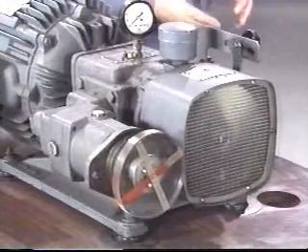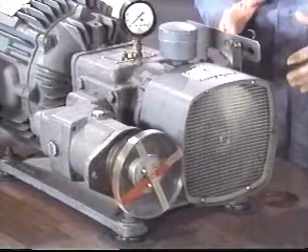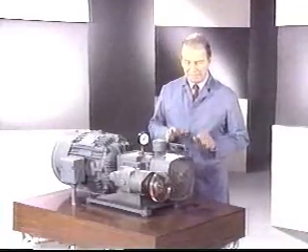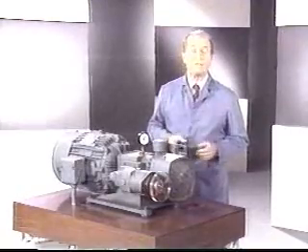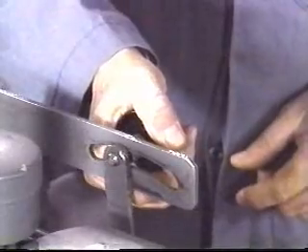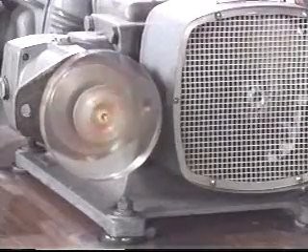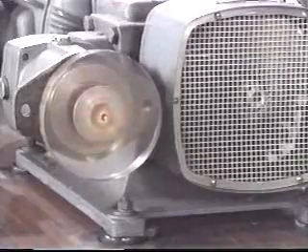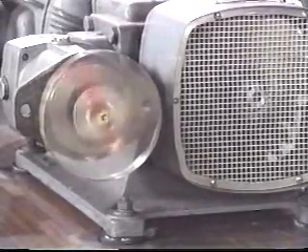Right now, the electric motor and pump are turning at 1800 RPM, but there is no movement of the motor shaft. Actually, we couldn't move it if we tried, because the pump yoke is centered, and its pistons can't move in or out of their bores. Moving the lever off-center causes the motor to rotate slowly. The more we move the lever, the faster the motor runs. How fast the lever is moved determines the rate of acceleration and deceleration of the motor. And of course, crossing center will make it reverse.